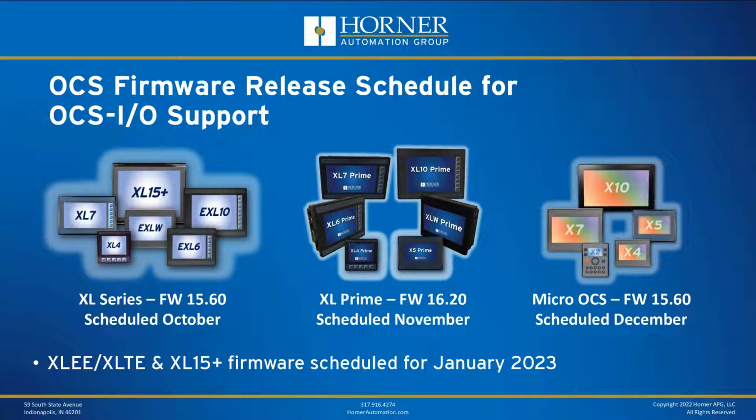He says, are the backplane modules all identical, or are they specific to a particular type of module? Yeah, definitely a good question. Yes, they are all identical. The same backplane connector will come with all modules, and you don't necessarily have to have the one that shipped with that particular unit mated with the particular module. They're interchangeable in that respect.